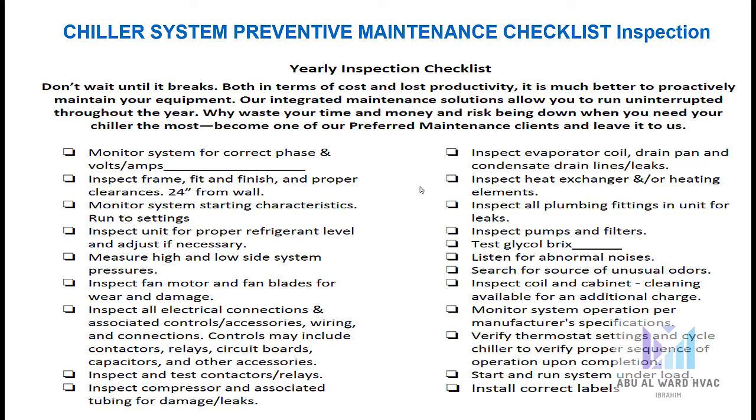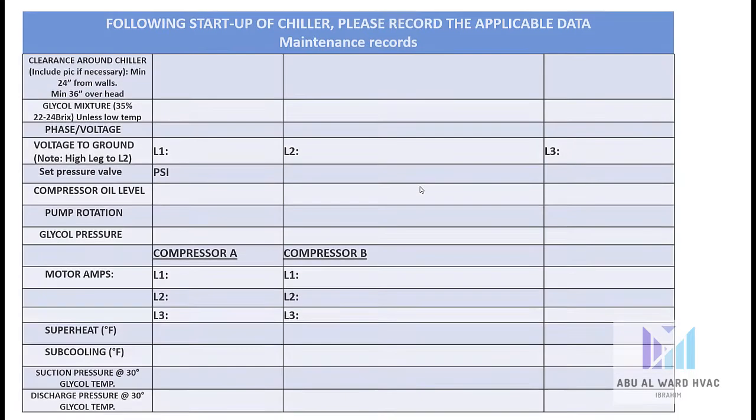cleaning available for an additional charge, monitor system operation per manufacturer's specifications, verify thermostat settings and cycle chiller to verify proper sequence of operation upon completion, start and run system under load, finally install correct labels.